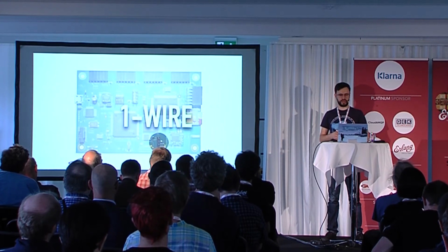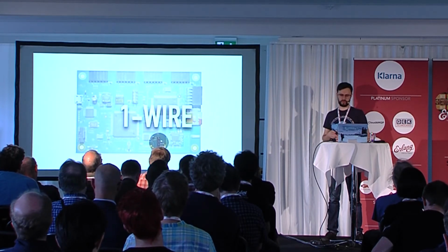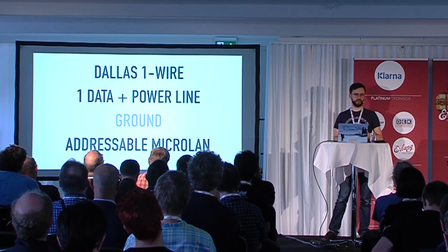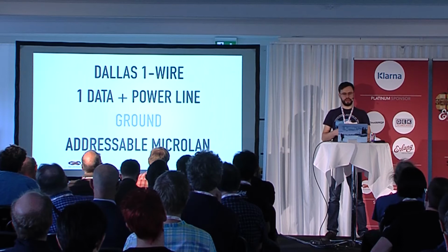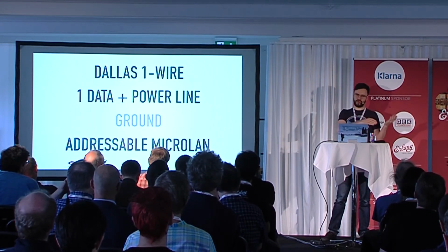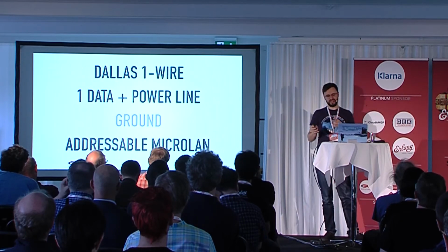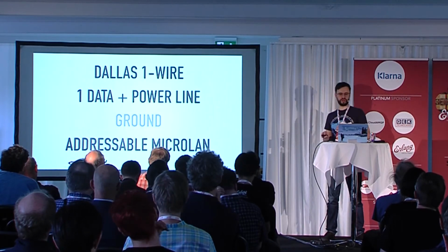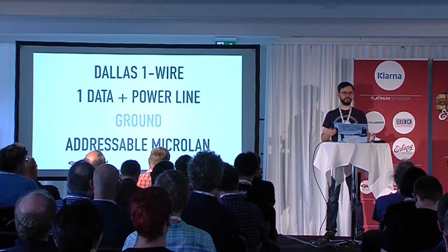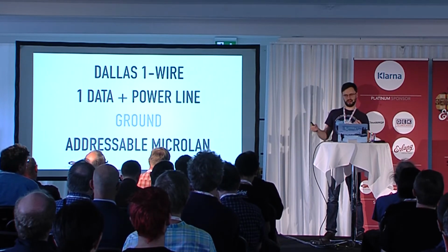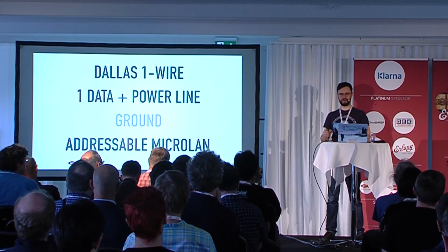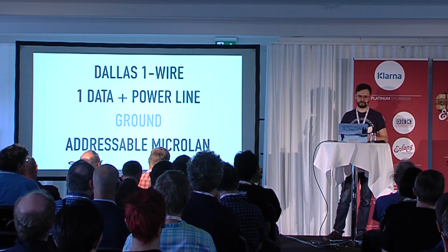And the last one we have is OneWire, a protocol called Dallas OneWire, developed by Dallas Semiconductors. What is cool about this one is that it's only 1 wire plus ground, so it's 2, but its data and power goes on the same wire. So when you have devices connected on this, they can charge themselves on the high. Whenever there's a 1 going on the wire, they also charge a capacitor, and then they use this to power themselves over time. So it's a really neat one.